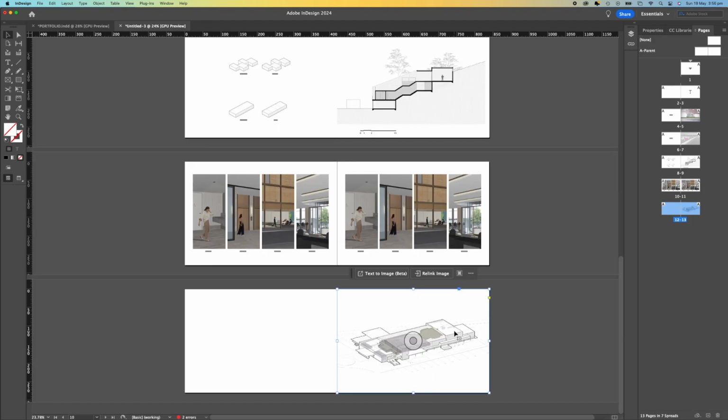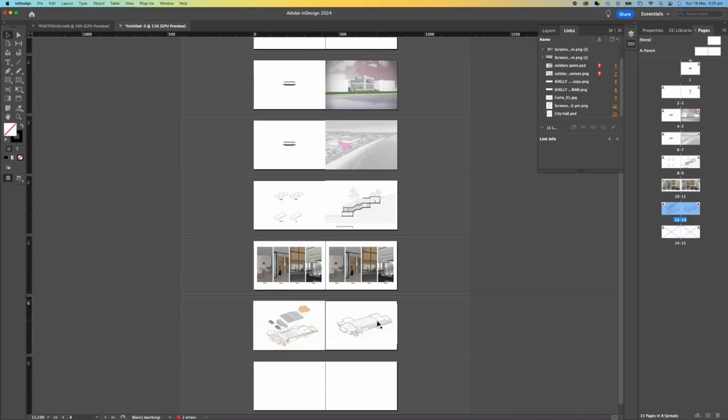Now that we've got our PSD at a nice size and fitting the sheet properly, we will select it, hold Alt down and drop in a copy. This will pick up another view that I have saved in the Photoshop file. So you can have multiple different angles of the PSD file that you're working with.